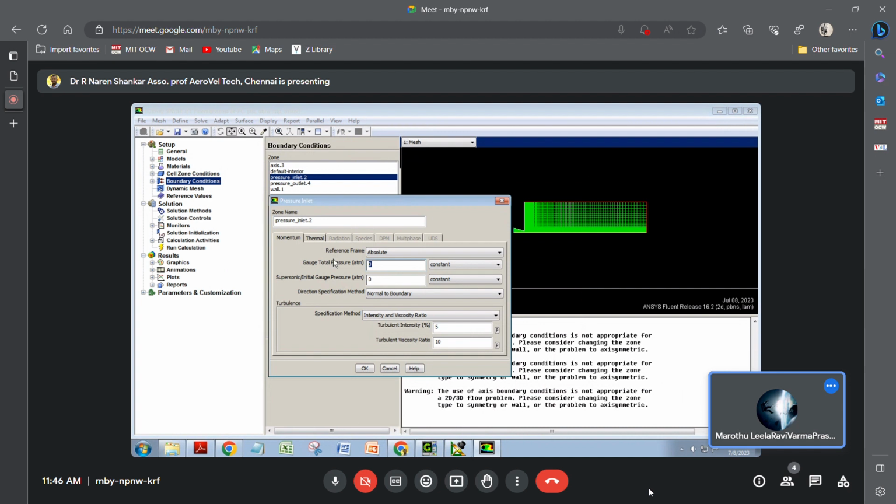If it is for Mach 1, sonic Mach number, I have given 0.89. Okay. We will do for a subsonic case, maybe for 0.6 Mach, so we will give 0.2755. So we are giving gauge pressure. If we add 1, it will become an absolute pressure. So click OK.